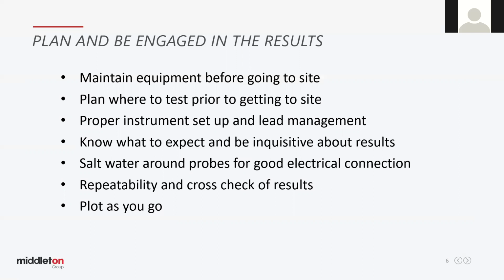Make sure all the batteries are charged if you've got battery-operated equipment. Plan where to set the tests, which we'll go through today. So know where you're going and what site you're going to rather than working it out when you get there. Have a proper instrument set up and lead management. So, again, as you'll see, we're going to be swapping leads around. So it's nice to have them colour-coded so that when you're swapping them around, if they get a bit tangled up, you're not going to get the wrong plug in the wrong hole to give you a wrong reading.